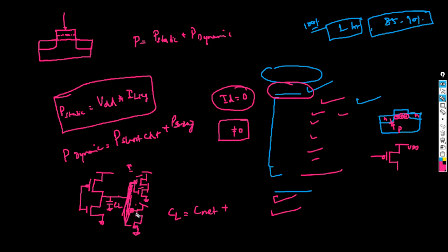There is a PMOS transistor and an NMOS transistor, and your pin is I. So your I pin capacitance is basically a gate capacitance, and this is the formula that would be used to calculate your load capacitance. Okay. Now let's quickly go and understand the meaning of charging and discharging.